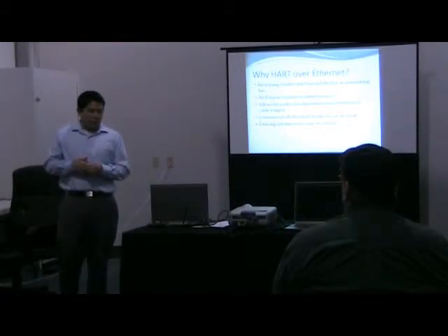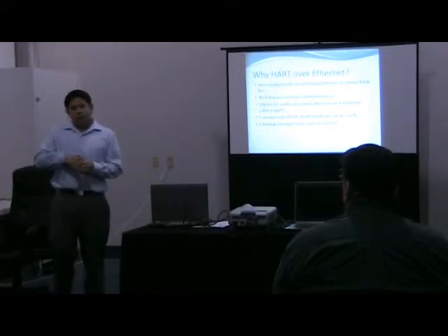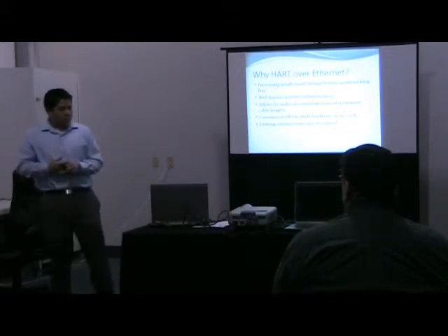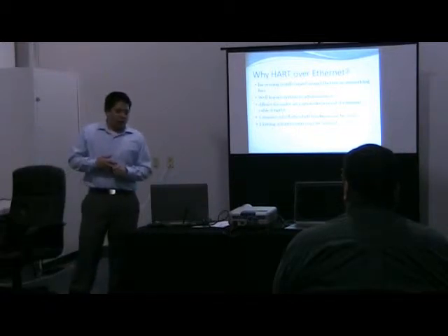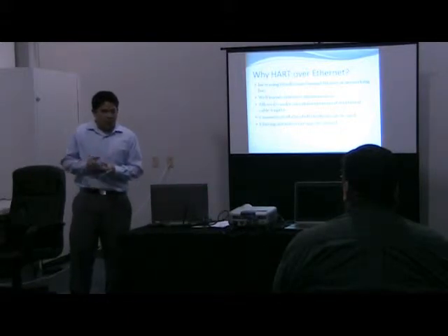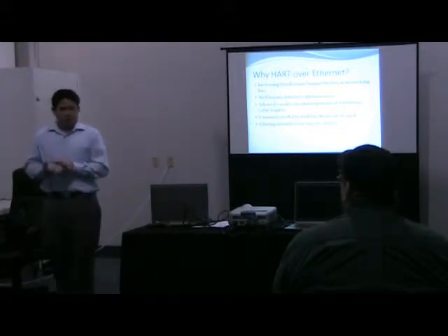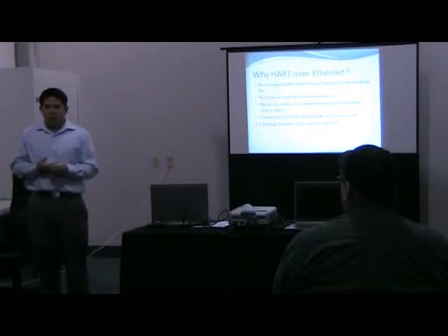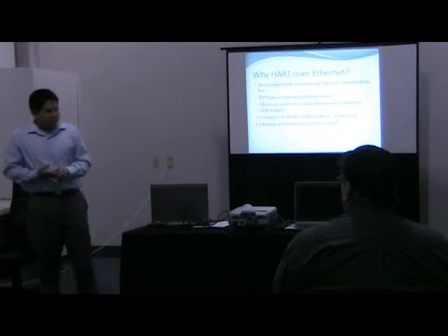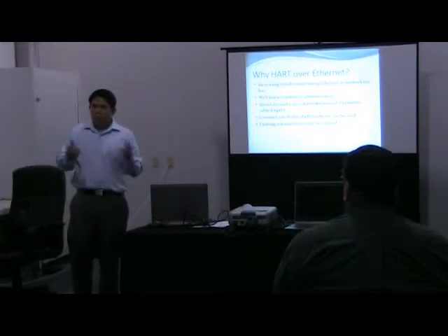Ethernet itself allows for larger area networks to be created beyond the traditional cable length. And you can use commercial off-the-shelf hardware. And because of this, a lot of times in some facilities, the existing infrastructure can be used. You may have a PLC that's already talking Ethernet up to your SCADA system, or VFDs to your PLC.